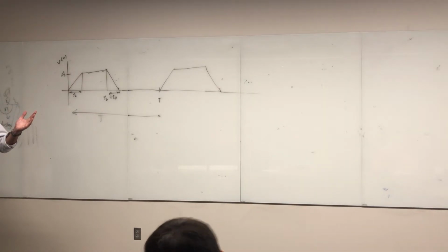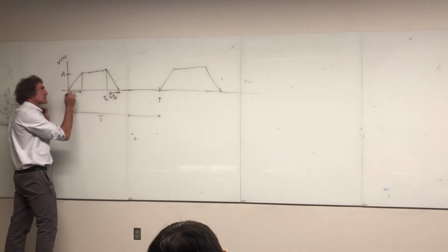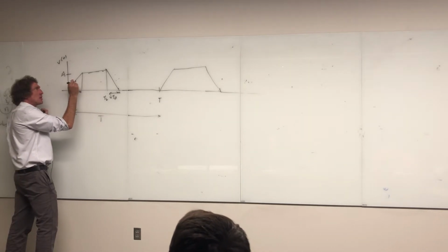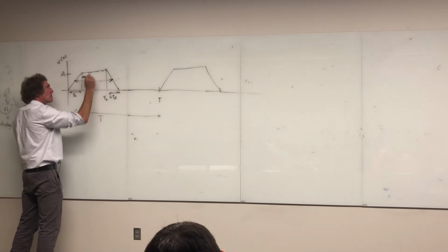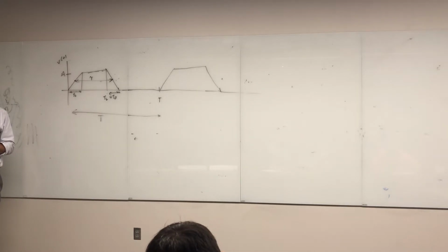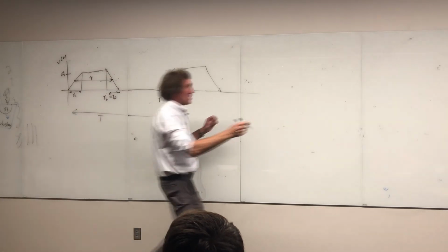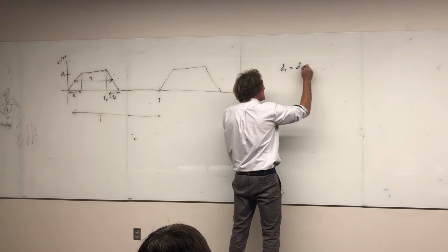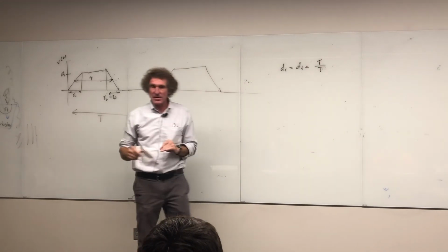Haven't you, class? All right, now this is the part I got to be clear about. This is the fall time, that's the rise time. We're going to assume they're the same. Go from the center, 50% point here, to the 50% point here and call that tau. Now that's called the on time or the up time. And then you can get something called the duty cycle or duty time. It's used duty cycle equal to duty time, and that's equal to simply tau over capital T. You have seen this before, have you not?